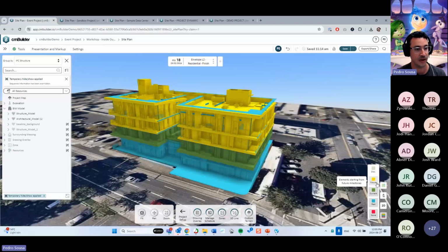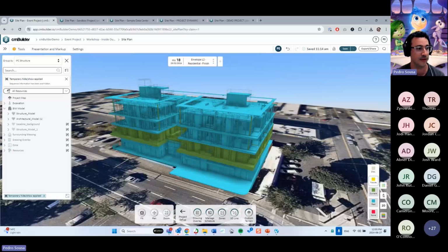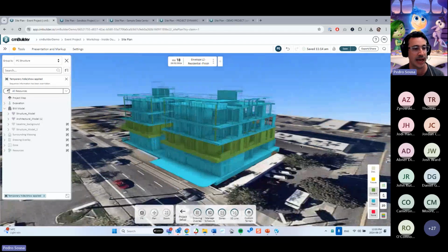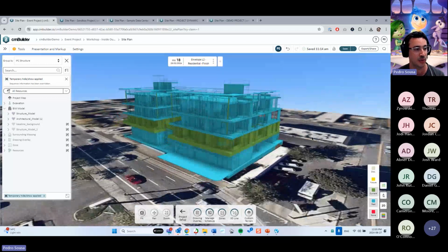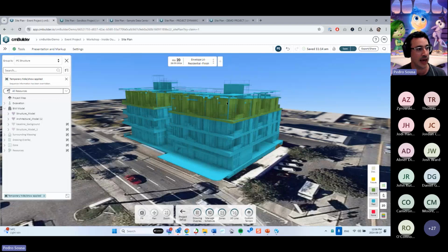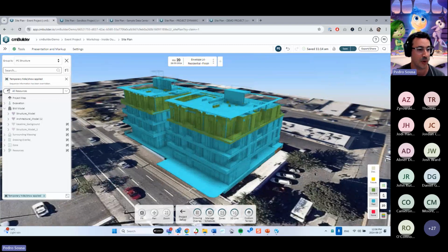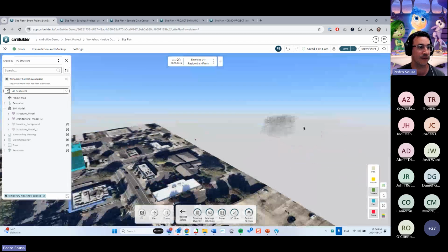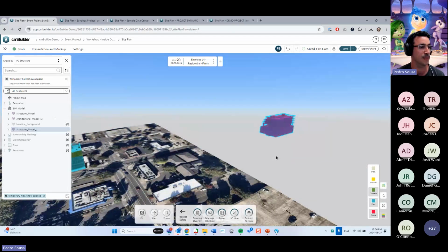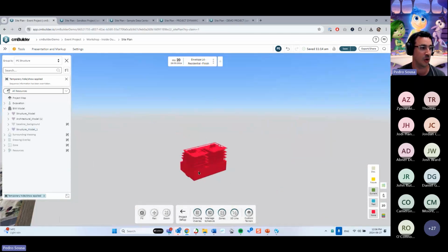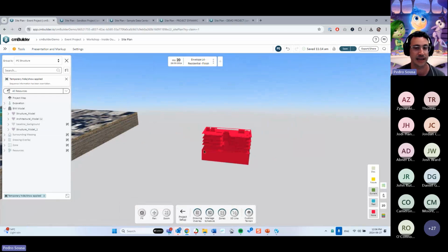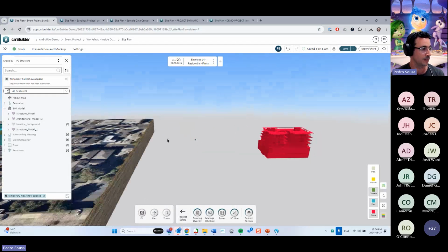So if I click on the future over here, it will deactivate and hide the parts that are tagged to show as future parts, right? So if I now move forward, I will see a highlighted view showing just the parts that are current and the past ones. And you can see that there is also a red part over here that's none. If I show this model over here, you see that this model is all colored in red because I haven't assigned any parts to any milestones in this model.